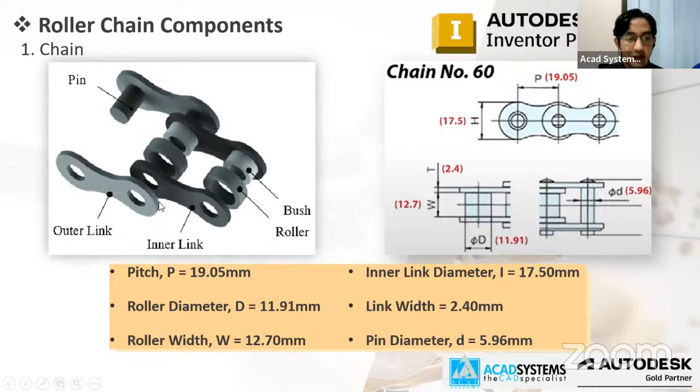The pitch is the distance between two holes. We have the roller diameter and width, then the inner link diameter. The outer link and inner link each share the same width, which is 2.4 millimeters, and we also have the pin diameter.